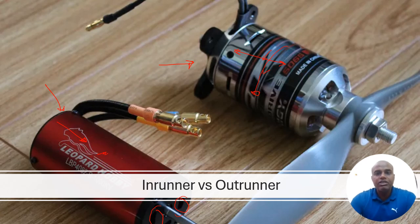The stator windings produce the electromagnetic field by the external supply, so it generates heat. When that heat tries to dissipate outside, my rotor is surrounding my stator winding and it is also rotating, so that heat gets trapped over here. It cannot exhaust from the inside to the outside. Therefore the heat gets accumulated over the shaft because it is being pushed by the rotor, which is running outside of the stator.